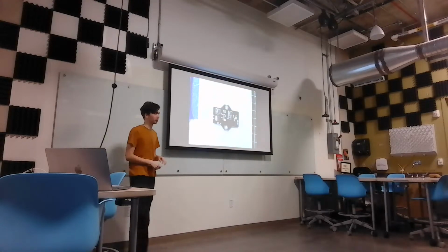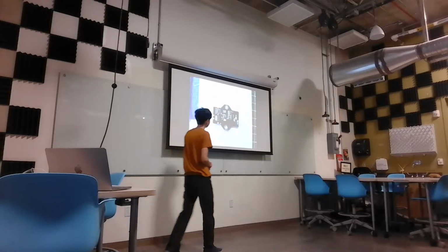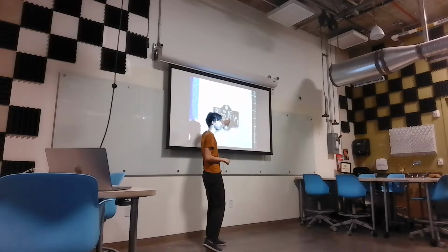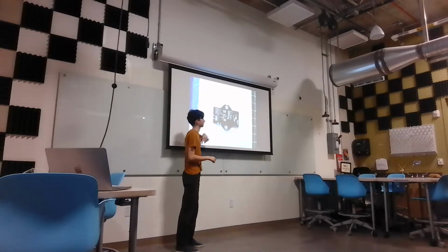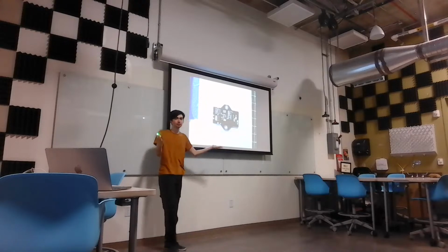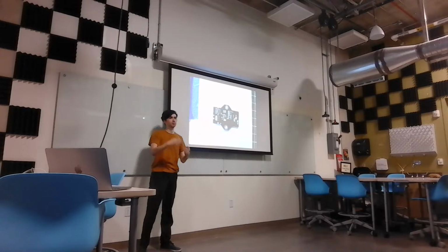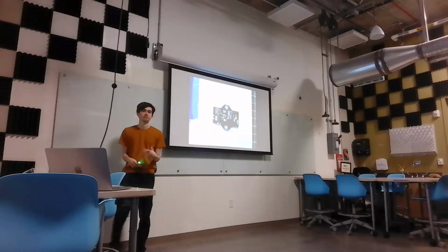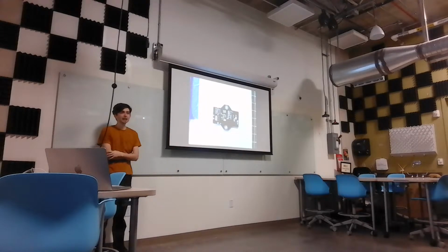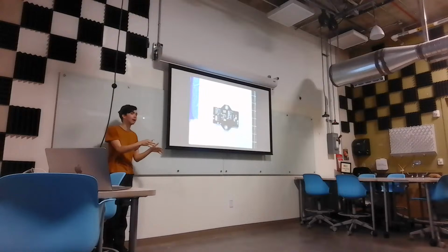Look how cute this little board is. So nice. That's the gate driver, these are the two FETs, and that's the microcontroller. Pretty simple layout, right? There's like 4 things. On the underside there are the passives, like the big old capacitors, the big inductor, etc. So I actually learned how to do this from a really amazing TI technical document explaining how to properly lay out buck regulators.